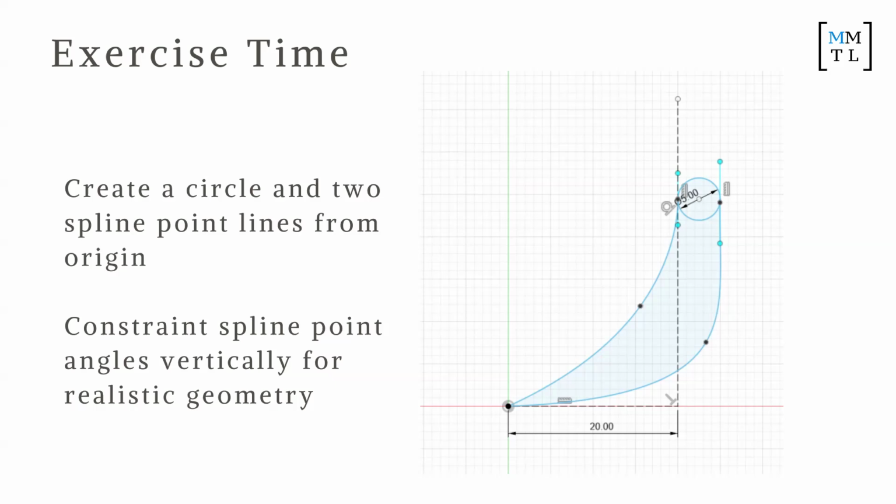And notice how here I've deliberately set everything to blue lines, so I haven't made extra dimensions or anything, because I want to be able to change it later on when I revolve. You guys will see. It's pretty fun to play around with. Oh, that's not good. You just draw a different one. That way you can make cool shapes.